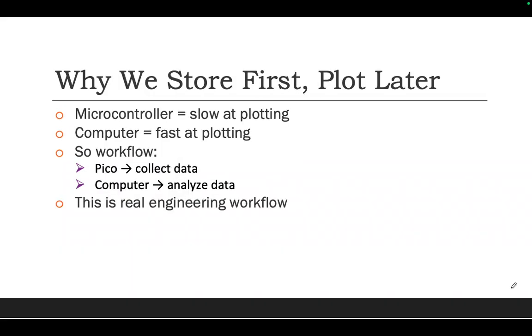You can see the microcontroller. We know it has a microprocessor in the RP2040, but the power is limited. If you deal with data, later you can use your own computer, which is very powerful. The microcontroller is slow at plotting and analyzing things; the computer is fast. So the workflow is you use the Pico to collect data, and then you use the computer to analyze data and plot. That makes sense to you? This is a real engineering workflow.